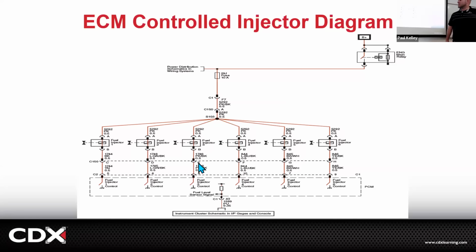But what if you go all the way down to terminal number 4 and there's no ground coming out of there? Yeah, down in here, huh? So the ECM provides the ground. If the ECM has a good ground, it can provide a good ground to 1, 2, 4, 5, and 6. The ground of the ECM is good. It's just this little transistor or switching contact, it's really going to be a transistor, is bad in the ECM. So you're like, this car needs an ECM. Maybe double check yourself because ECMs are pricey. But if that's still what you got, the ECM could be bad.